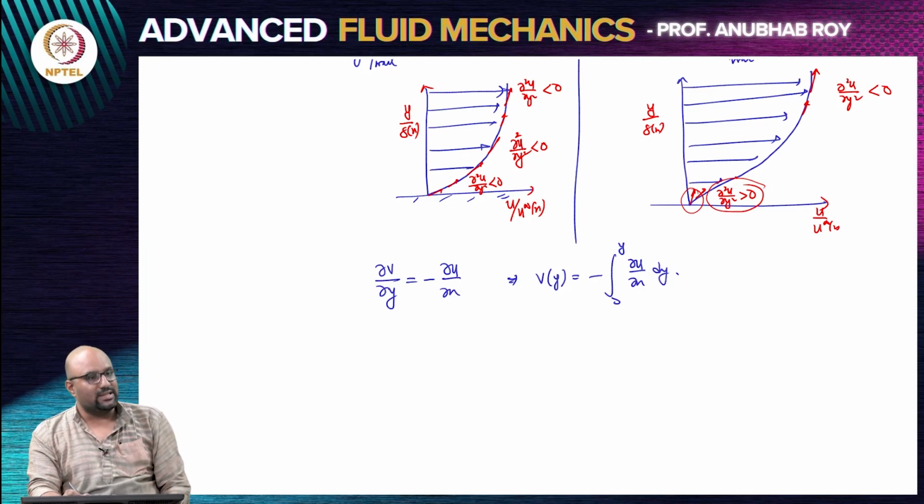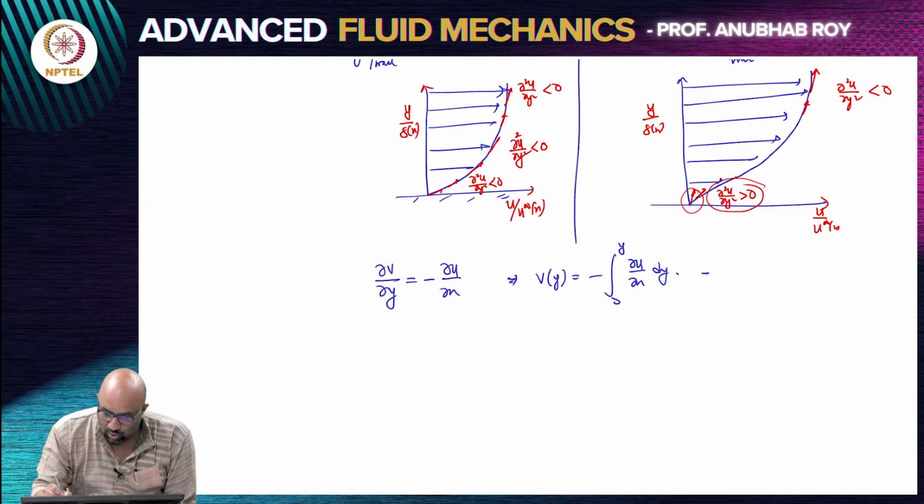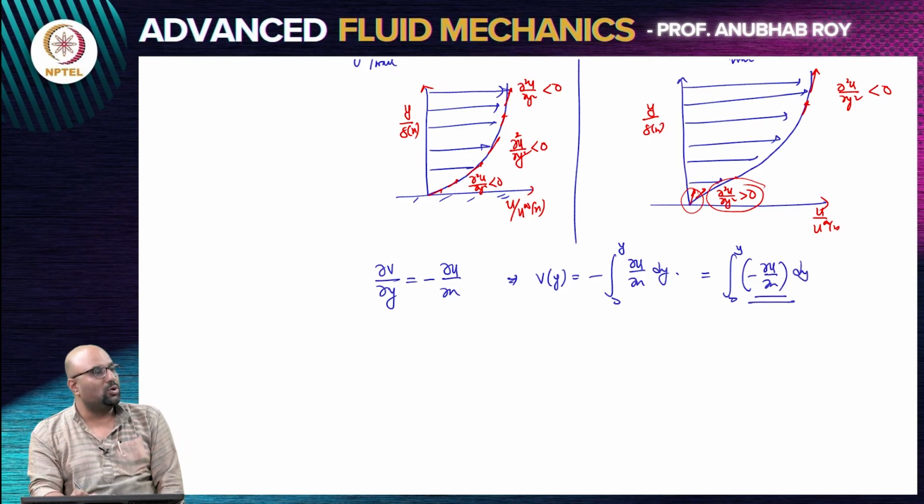Viscous diffusion is basically what is responsible for the transverse or the wall normal velocity. But here you can see that if you have a decelerating stream, minus ∂u/∂x is positive. If the stream was decelerating, then advection will also give you substantial increase in vertical motion.